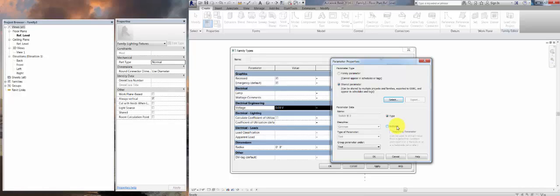Switch ID 2 is the parameter we use to create light groups, that is, the identification that tells you which fixtures go with which switch. Revit has a switch ID, hence the name switch ID 2, but it only allows you a 1-to-1 ratio between fixtures and switches. And oftentimes, in the modern day, when we have lots of digital switches, this is very limiting. So we use switch ID 2, which is used in schedules, tags, and in both fixture devices and electrical lighting fixtures.